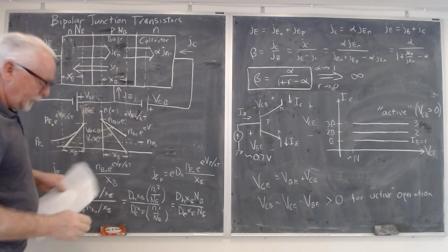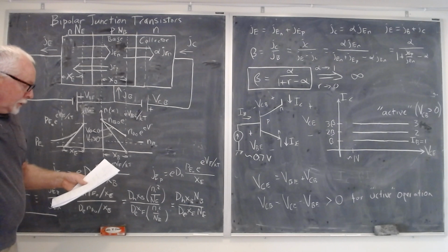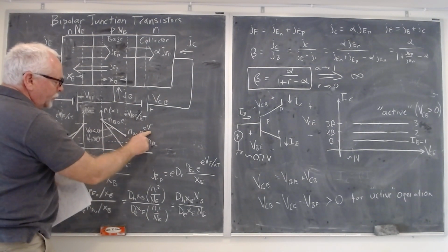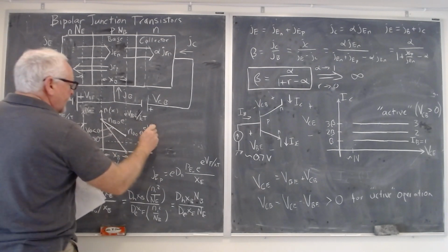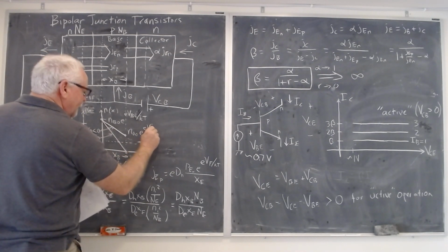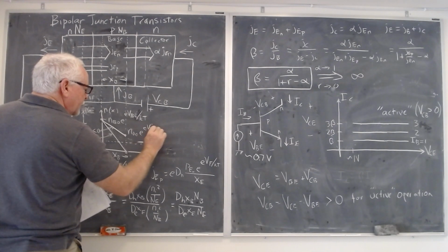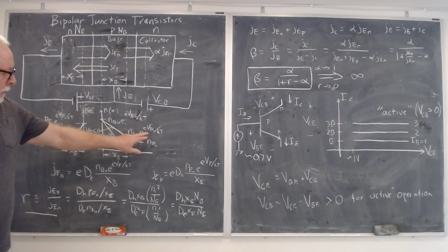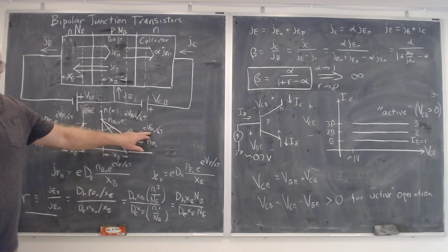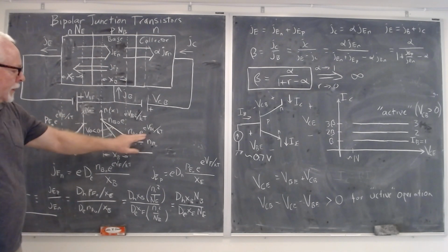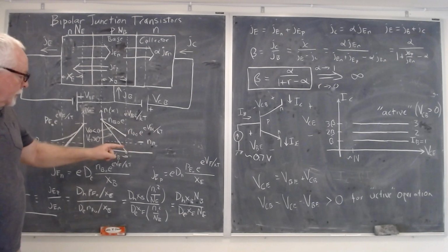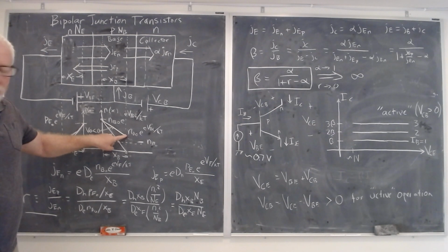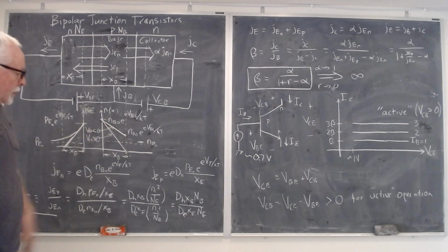Now we got to be careful with our designations here, because remember, to get this value we have to put the forward bias value there, and so that's actually now VBC over kT, which basically means as VBC, the voltage of the base with respect to the collector, becomes positive, that then lifts this up, okay, and it has some non-zero value.